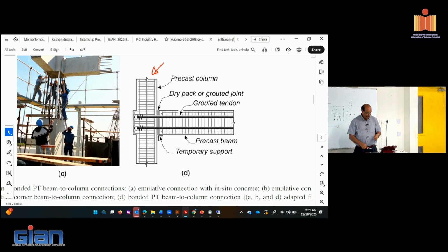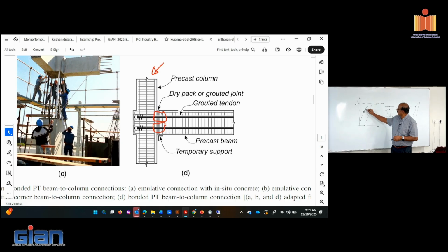So what happened was that in this region, you basically damage the grout locally. As you damage the grout, it becomes debonded in the localized region. So once it became debonded in the localized region, the strain is not concentrated. So the increase in strain is not going to go from here to here.